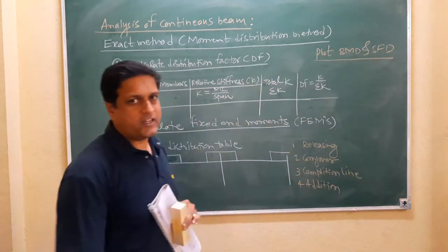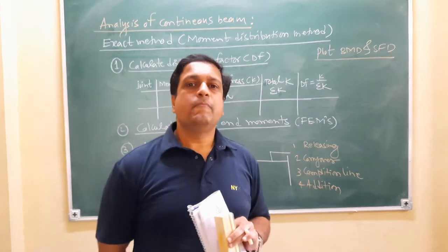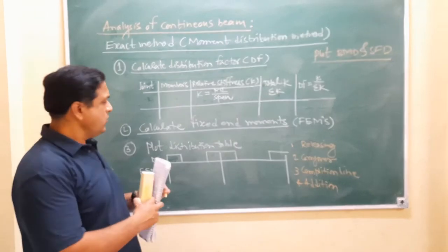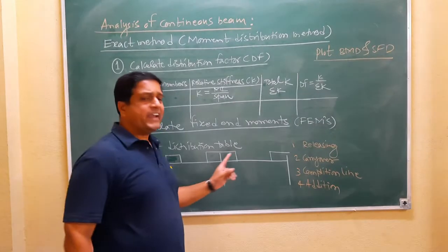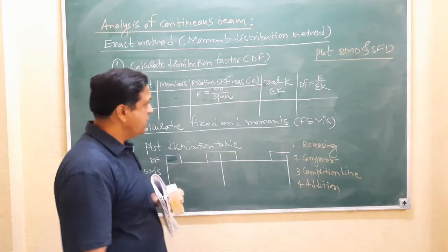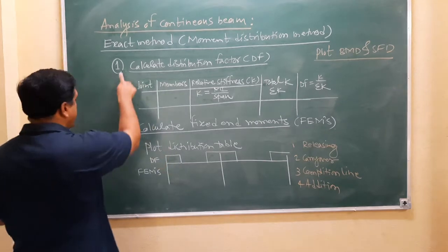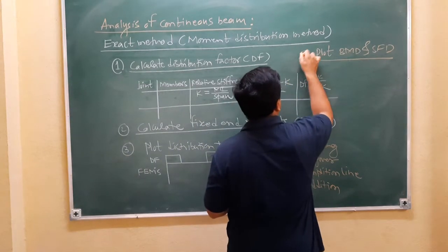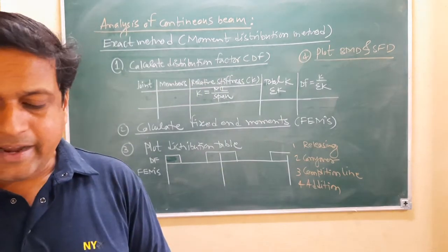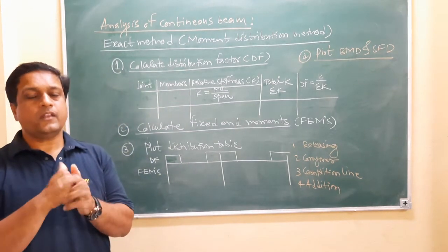Using that bending moment diagram and shear force diagram, catch the peak moments and design the beam. But I want to remind you, these iterations are carried out till the equilibrium conditions are satisfied. Do these steps, 1, 2, 3, and the 4th step is plotting of BMD and SFD, and take the maximum shear force and bending moment, and do the design.